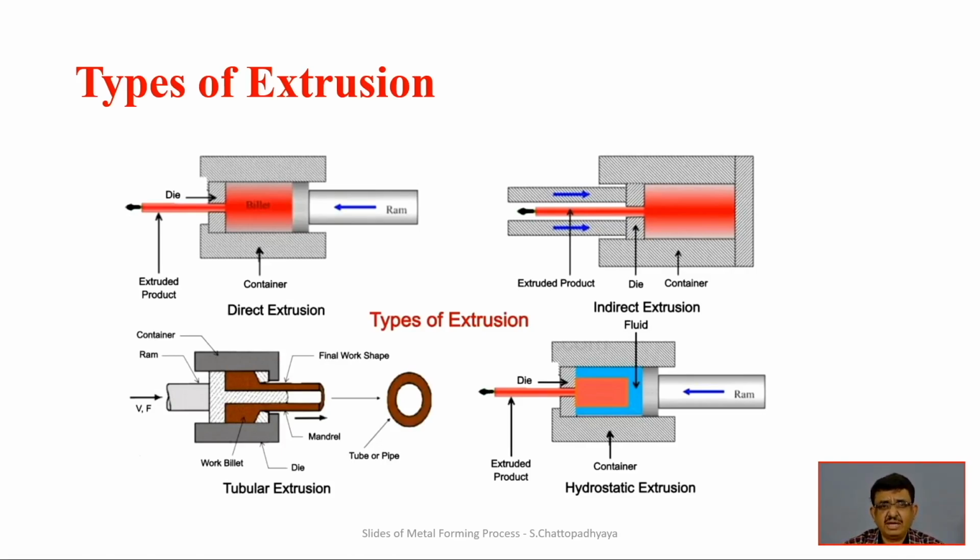And the fourth one is hydraulic, where hydraulic fluids are there. Hydraulic fluids are pressed against the ram. The ram is not directly pressing the material. Hydraulic fluid is pressing the material. The advantage is that hydraulic gives very, very enormous pressures, but it is stepless. It is uniform because of Pascal's law, and they are pressing the material against the die, and the die